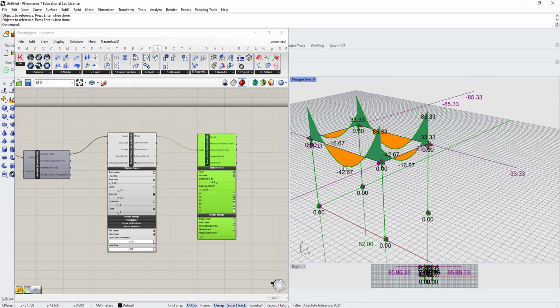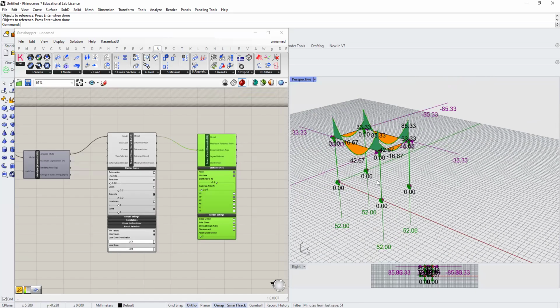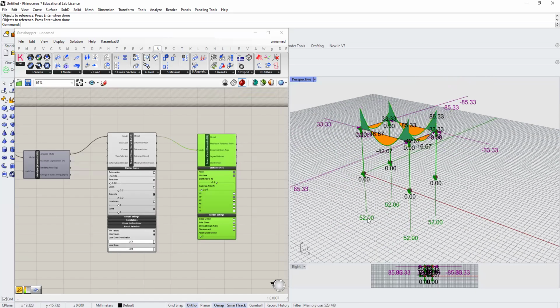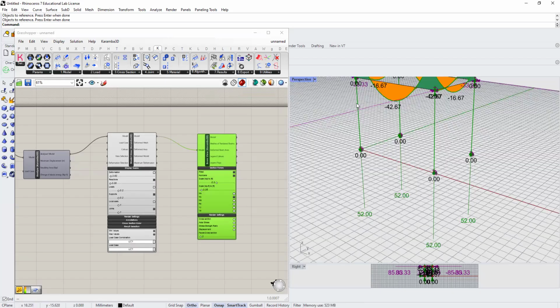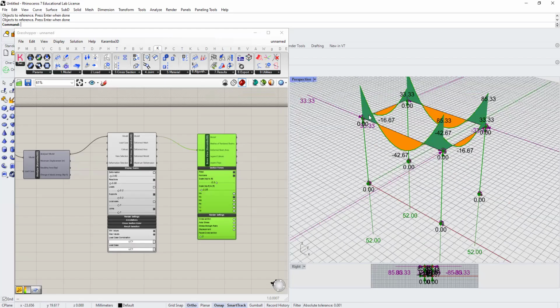about designing the beams. Then if you want to design the columns as well, you should look into the axial forces going through the columns, which are actually the reactions. Since here we picked the connections all rigid, no bending force is transferred to the columns, so they're just under axial compression stress by the support, which is 52 kilopounds.